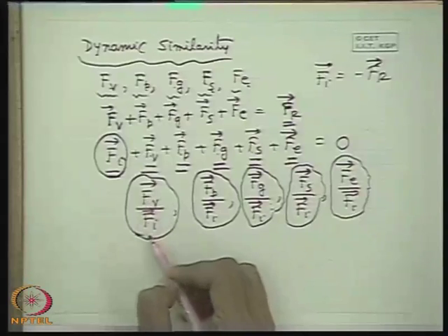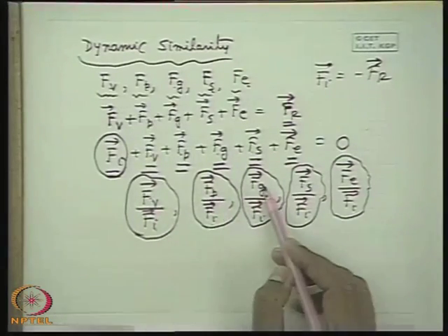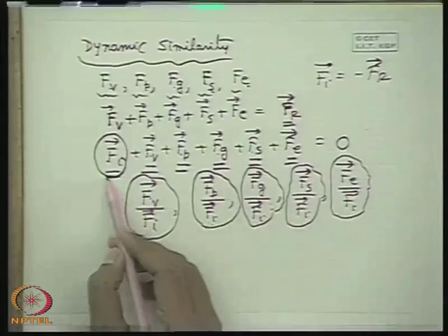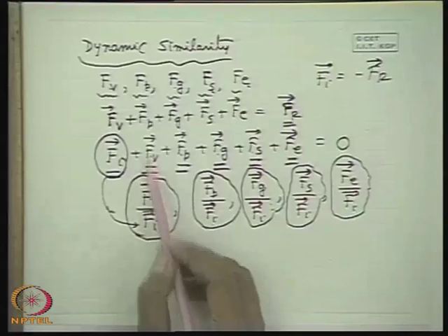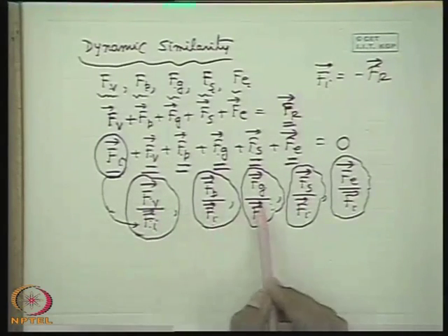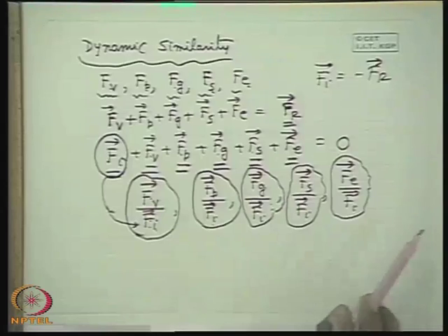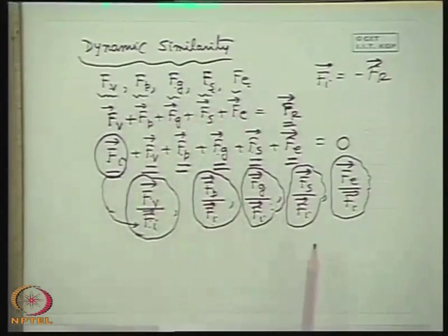practice. These are the ratio of viscous force to inertia force, ratio of pressure force to inertia force, ratio of gravity force to inertia force. So this is a common practice to take inertia force as the reference force and define the ratios with respect to this. So in general we get five ratios for a fluid flow problem which is being caused by all the forces.